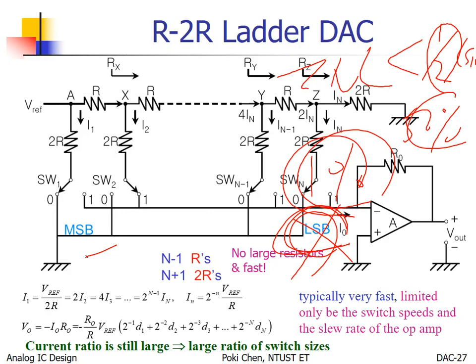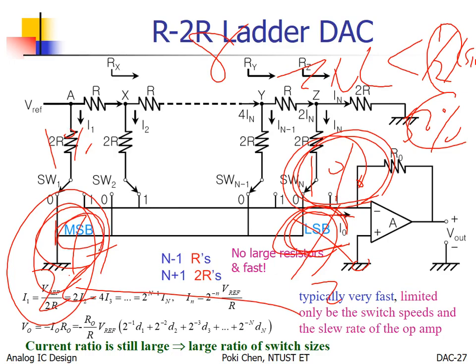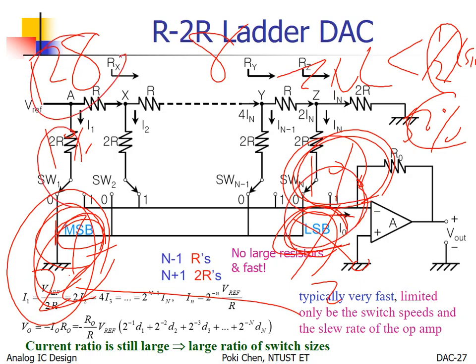Right now if you have 8 bits, LSB 2 to the 0th power all the way to 2 to the 7th power, 1% here, you still get 1% in yourself, but the weight of MSB is 128 times higher than LSB. So 1% for MSB means 128% for LSB. Got it?